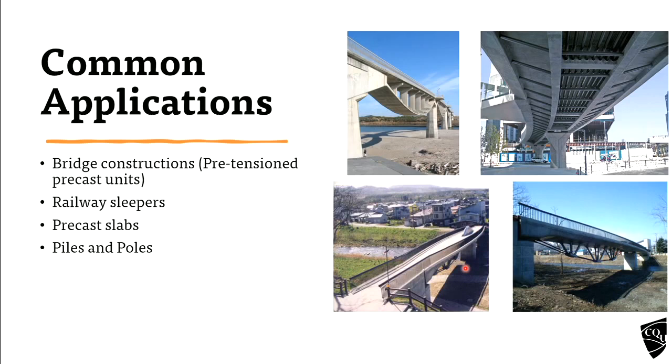So I think this was built in early 2000, or 2001, or end of 1990s. So around that time. So that is external post tensioning. I will explain that one in a minute. But it's called external post tensioning. So the pre-stressing wires are completely outside and connected through some connectors to the deck.